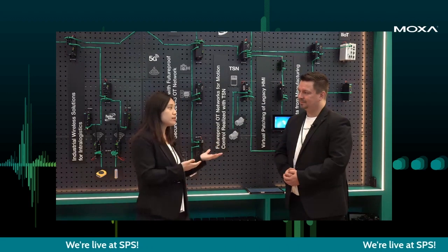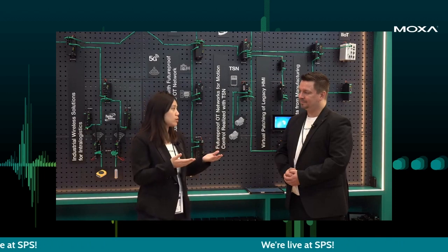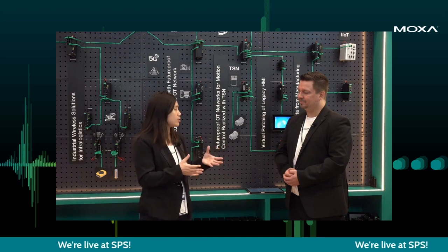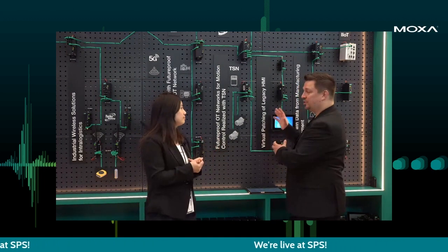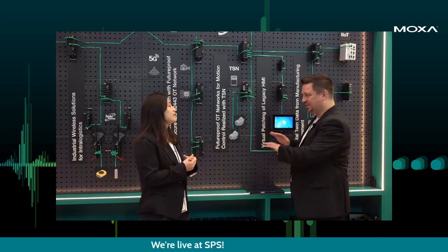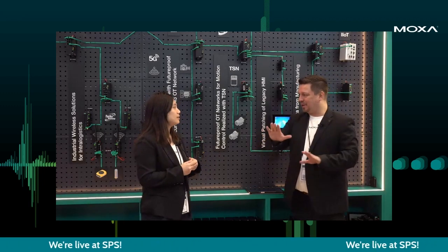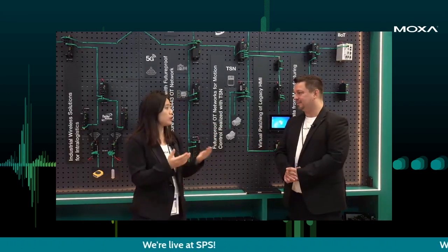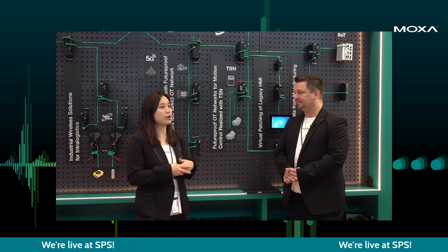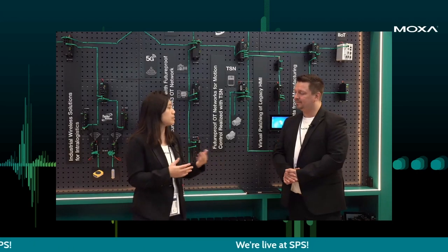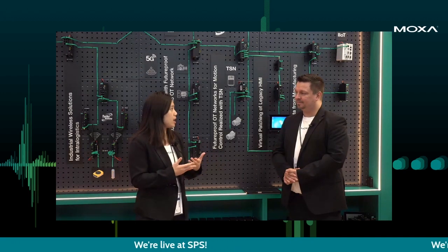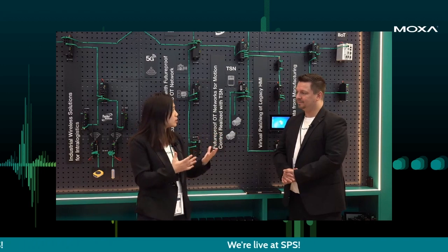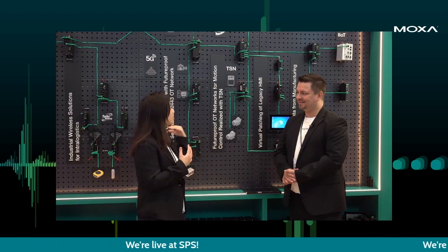But that creates a lot of effort on the operation and maintenance side to have distinct networks. Now with TSN, we are able to run both non-critical and critical data on the same network, without worrying about any delay in the transmission of critical data. So it is a real converged network with the foundation of gigabit always inside, which is enough bandwidth to make sure everything is handled. That is how the TSN-G5000A series supports 802.1AS and 802.1Qbv for time synchronization and also deterministic transmission. And of course, the switches are designed with IEC 62443 in mind, as all of our solutions are.